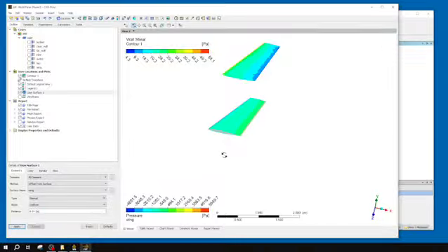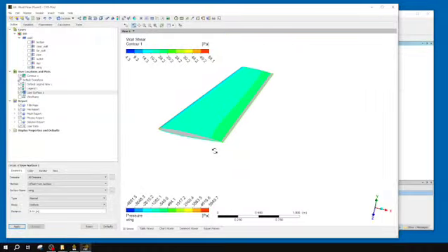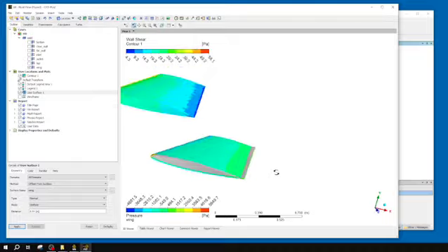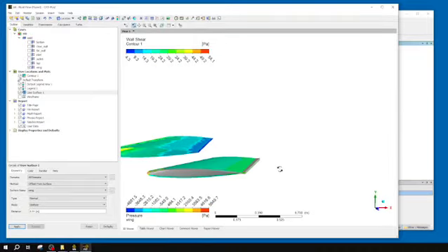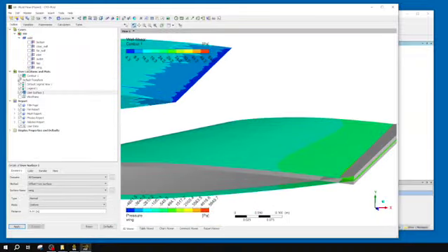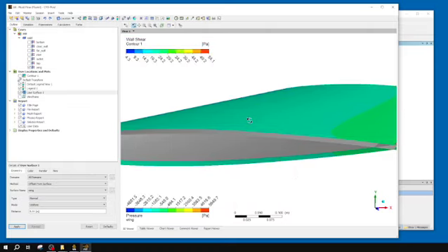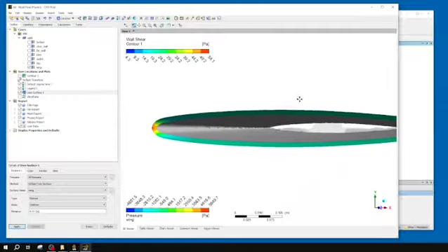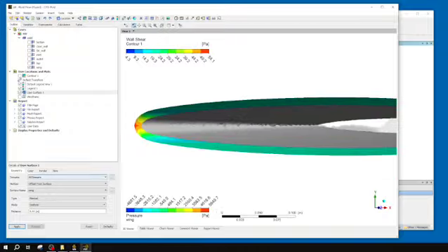So now that it's finished running, that actually took quite a bit longer than I was expecting, but partially because I made a small little mistake. So if I zoom in here for you, I'm going to uncheck my contour, so that's not in the background. You can see it actually generated our little surface on the inside of our wing. I wanted it the other direction, so I just need to slip in a negative here, and then I can apply it again. And then hopefully it doesn't take as long, and it should flip out to the outside.